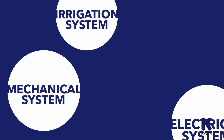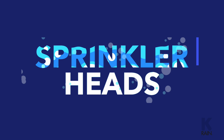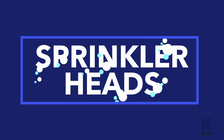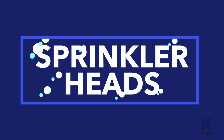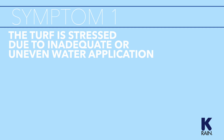This course will focus on the mechanical components: sprinkler heads, valves, and pipe. We'll discuss how to diagnose common problems with each of these components and how to solve these problems quickly and efficiently. The most common irrigation system problems associated with the sprinkler head are coverage problems, leaks at individual sprinkler heads, and obvious sprinkler failure. We'll discuss each of these in turn, identifying the symptoms, discussing the potential causes, and recommending a solution. Symptom number 1. The turf is stressed due to inadequate or uneven water application.